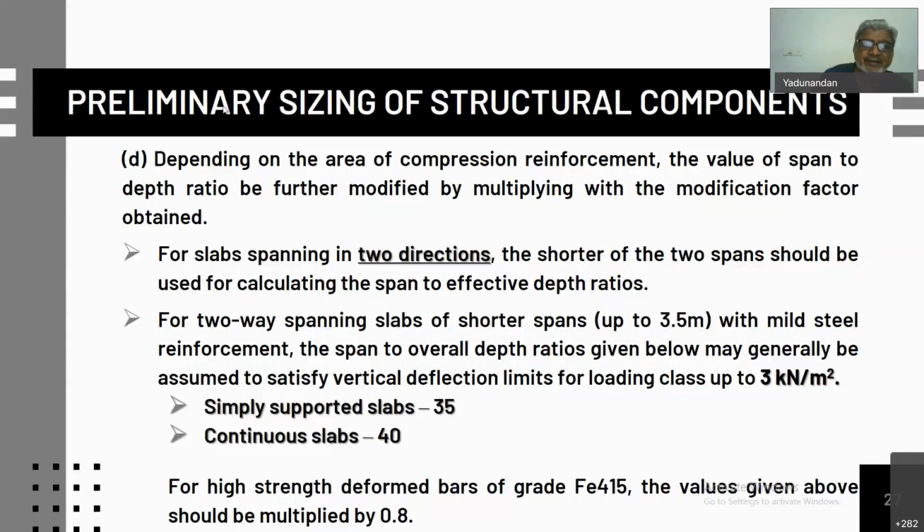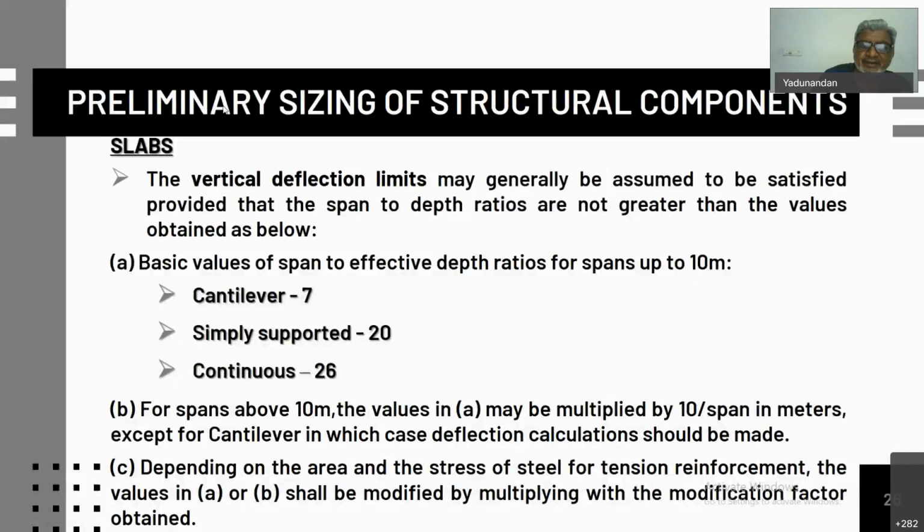Of course, all except for the 250, the 415 and 500 have to provide higher thicknesses when compared to the Fe 250 steel, because to get the full action of the reinforcement of higher strength, we require larger depths. But the tension reinforcement and compression reinforcement reduce the deflection, therefore they have a contribution.